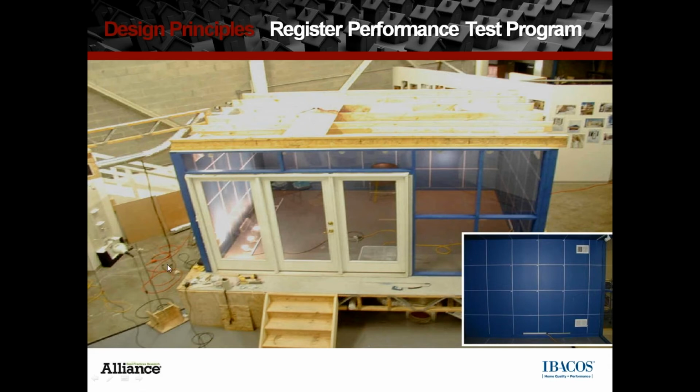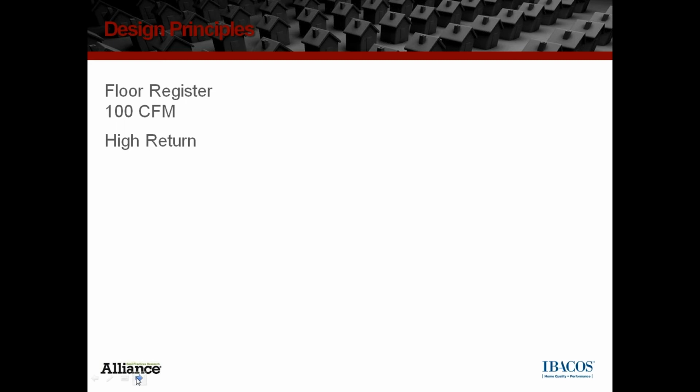If a picture's worth 1,000 words, then a couple moving pictures might be worth 10,000 words. The next couple of slides are based off a study that IBACOS did from 98 to 2002, where we built this room back in our shop area and set it up with some registers and injected smoke-filled air into the room so we could see how the air performed within the room. I have 3 different scenarios to show you. One is the typical floor register, one is the ceiling register, and one is the high sidewall throwing register. And they're all at 100 CFM, so the same volume of air is being delivered to the room.